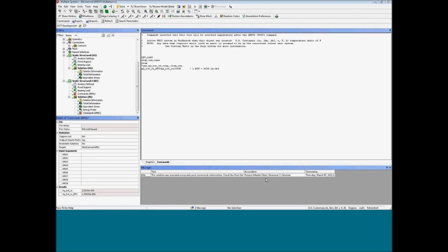This has always been one of the concerns with Workbench, the lack of consistent units in classic ANSYS. Workbench converts all the British thermal units, or basically the BTU quantity, into equivalent pound units when it goes into classic ANSYS. So when you have the mechanical database and you export or run it, it's going into classic ANSYS. All material properties, loads, anything that needs to get converted to consistent units does. That also means that in post-processing in classic ANSYS, those are still in those consistent units, but Workbench converts them back. So that's really the key here, just remember that that's the case. It's easy enough to convert, as long as you're aware of that.